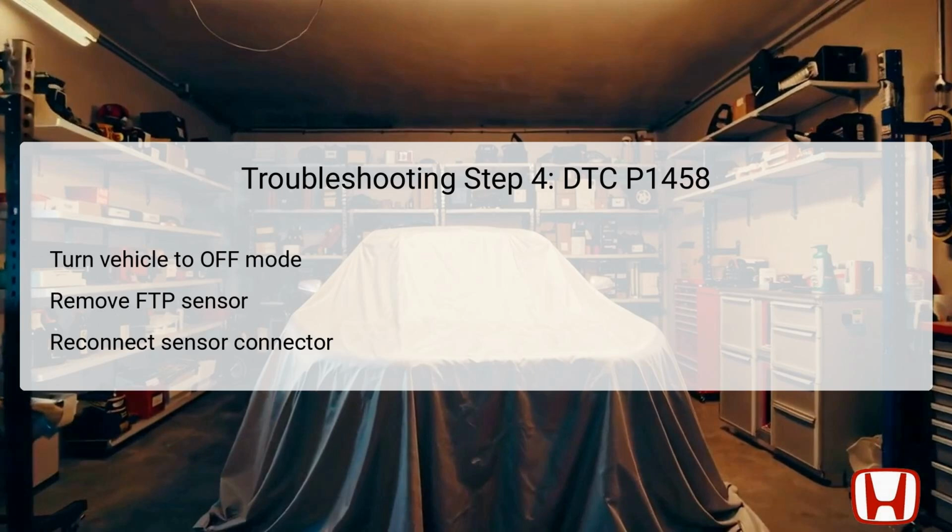If the readings reflect a variance of 0.067 kilopascal, 0.02 inch of water, 0.5 mmH2O, or more within 3 seconds, then the sensor itself is deemed to be functioning correctly. However, if the readings are still not satisfactory, consider that this may indicate an intermittent issue once more, and proceed with checks for wiring connections, or even suggest sensor replacement if necessary.